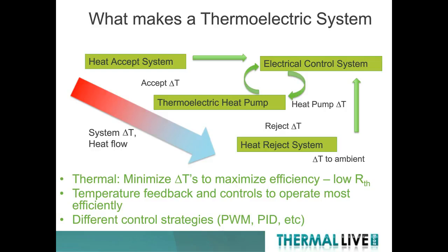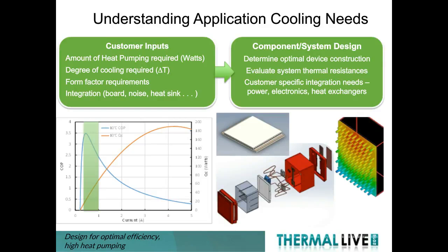This ties in very well to the concept of variable capacity. So as the voltage or current or power input changes, the capacity and the efficiencies change with respect to that. If you do not control that effectively, you can have a system that is very, very efficient thermodynamically, but very poorly controlled and regulated. What that means is the devices themselves act as essentially a resistor.